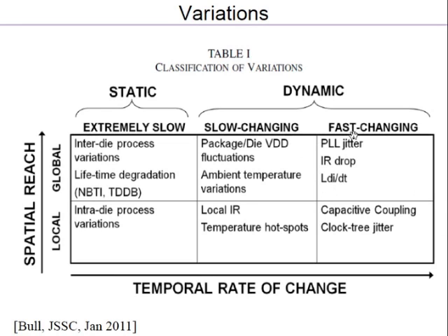And these changes could be global. That means the clock is coming from a global source, so the period change is uniformly seen by everyone. Or it could be local, because you have this clock in a local region which has coupling coming from another signal, so the period changes locally for that small group. So you have all these changes, and the engineering design is in some sense to make something work reliably and robustly. All these had to be accounted for, and usually they are accounted for by a simple way of margining.